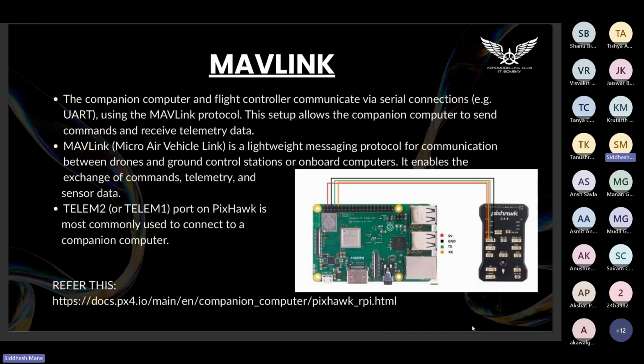Now we saw that there's a flight controller and there's a flight computer. These two have to communicate with each other. Say the flight computer has taken footage of a particular area, it has scanned, but it has to tell the flight controller, right? Because the flight controller is driving the drone. They communicate with each other with the help of MAVLink.